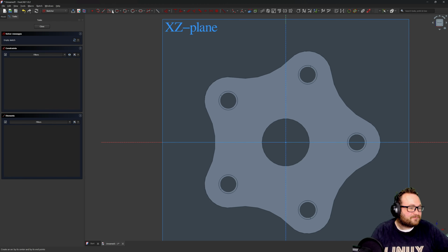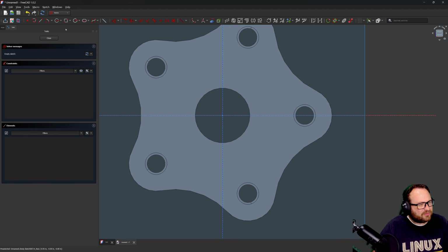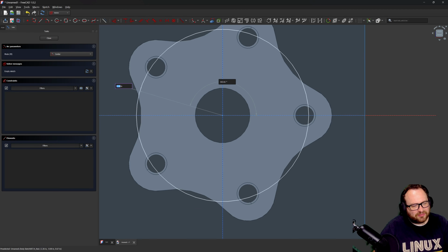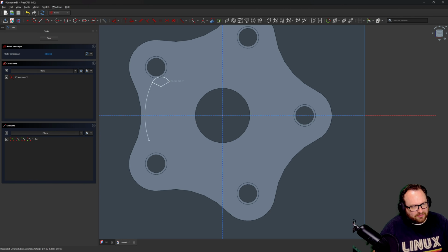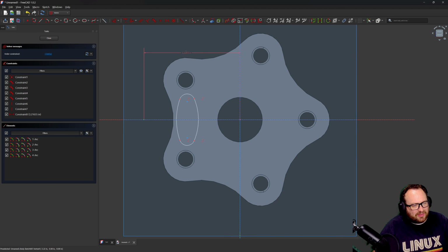So for right now, I'm going to start sketching here, and I'm going to start by making an arc that is centered around the origin. And then I'll grab a polyline, and again, just use 3 M's, 3 M's, 3 M's, and then we're going to say T for tangent, V for vertical, and we'll make sure the endpoints of each arc here are vertical. I'm going to say D for dimension. We'll take that arc endpoint and make it 2 inches. We'll make this arc 0.125, and the other one will size accordingly, of course.